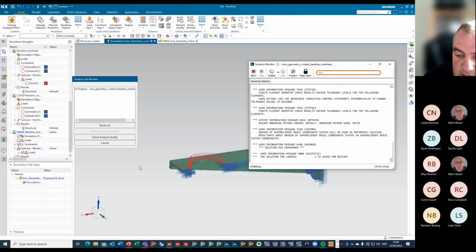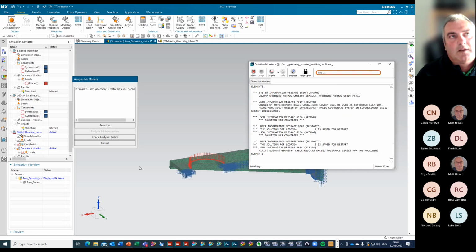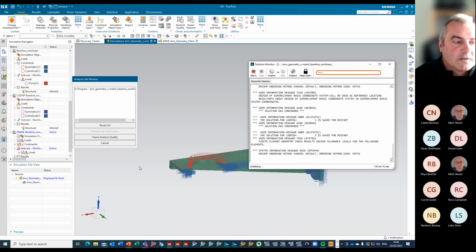So you can have a nonlinear curve, but if you don't put the switch on, it'll just take the first 2 points and work out the E value and apply that to it. If you switch on MAT-NL, then it will track the curve. So there's different nuances or ways that you apply it in the different solvers.